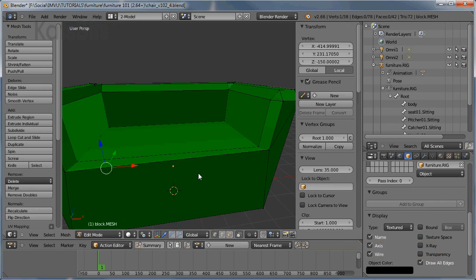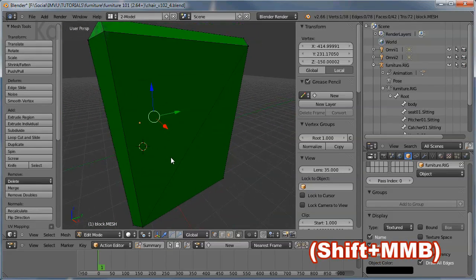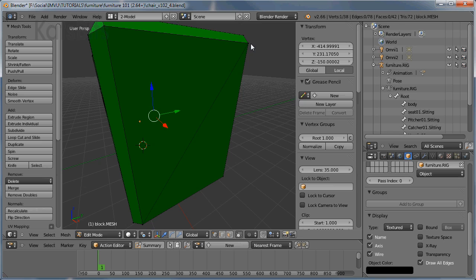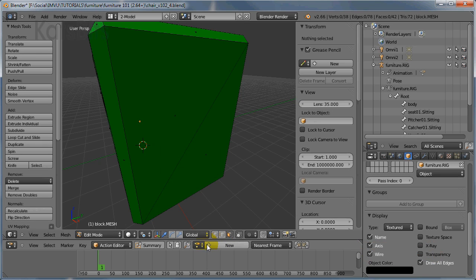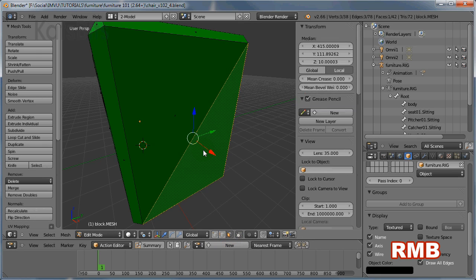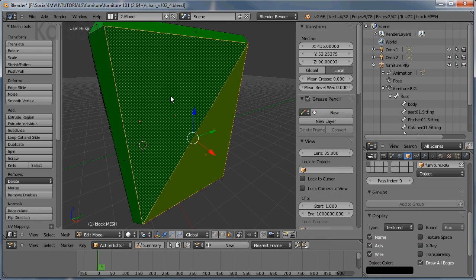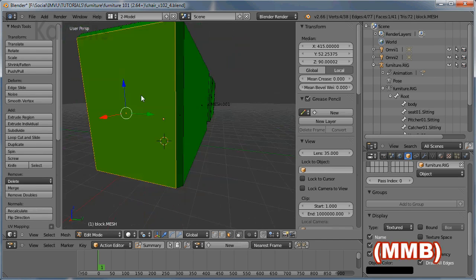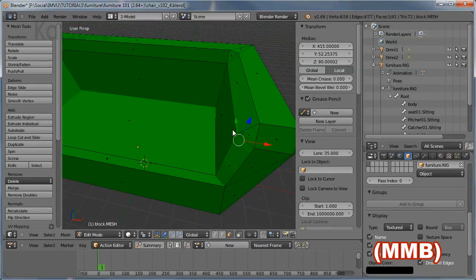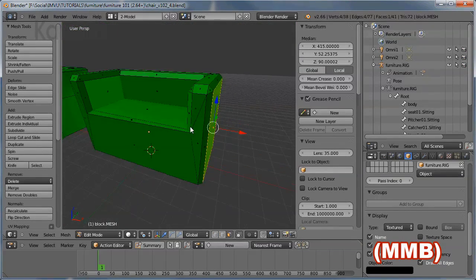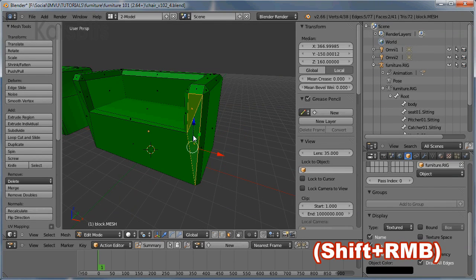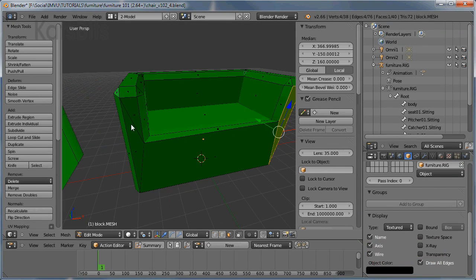And then finally, because this surface was split in half accidentally through merging, we need to join these surfaces together. So Control Tab, select Face, or click the appropriate Select button. Right mouse click, Shift right mouse, and then Alt J to join them together into a single surface. Then do this again along the front of the mesh to remove any other triangular surfaces that can be joined together to form a unified or single face.